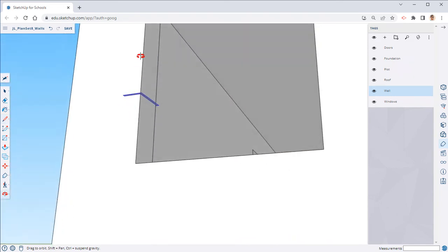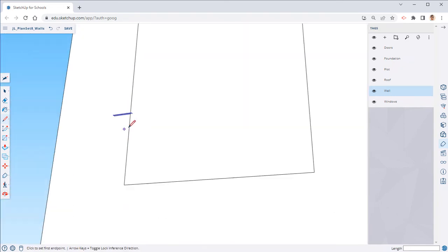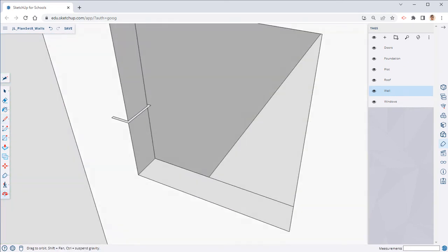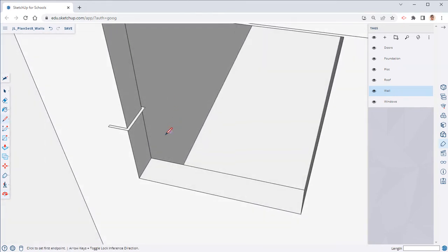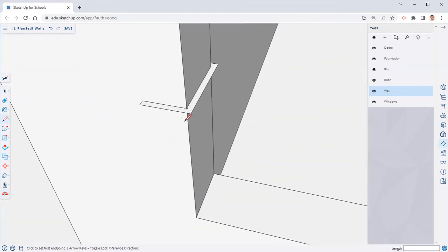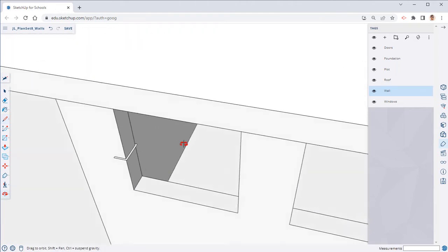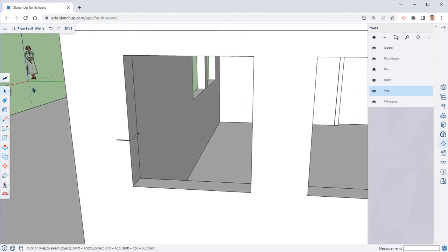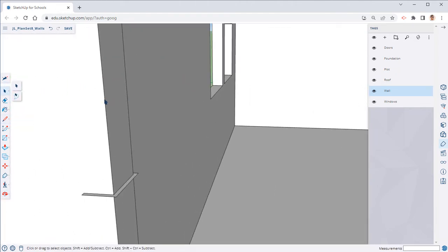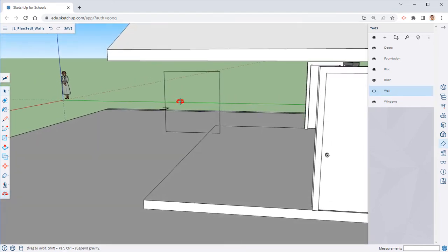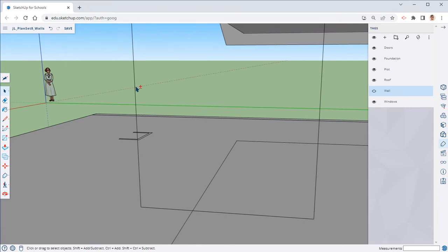Make sure that you go on this side as well. Erase that center thing. It doesn't create a line for us there, so we don't have to worry about that part. Get your selection tool again. You can come in here and, if you need to, turn off your walls after you create your lines. Hold down Shift and let's select all of our lines.